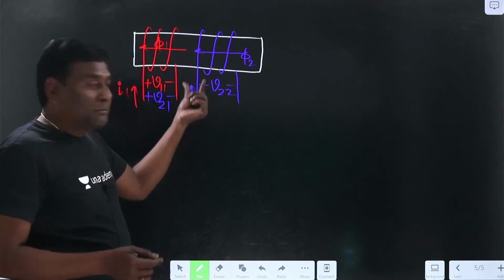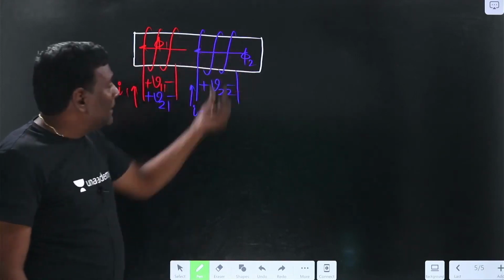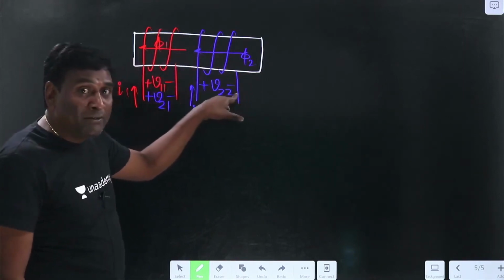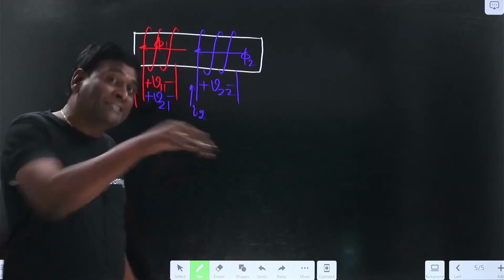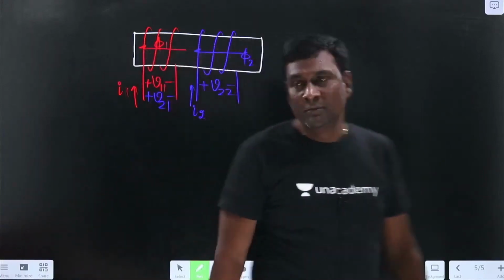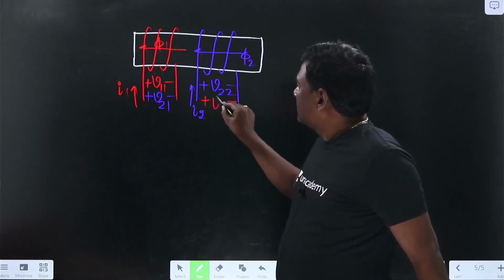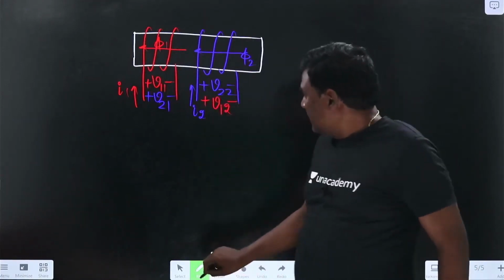Now it means phi 2 is there, phi 1 is there, phi 1 is in aiding direction with respect to phi 2, and because of phi 2 self-induced voltage is there, because of phi 1 mutual induced voltage will be there. That induced voltage should aid self-induced voltage or not? Yes. So here it is going to be plus, here it is going to be minus, because of first flux induced voltage in the second. Now let me draw